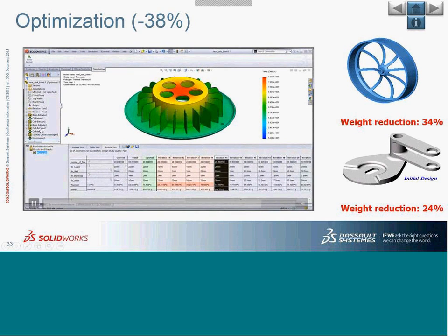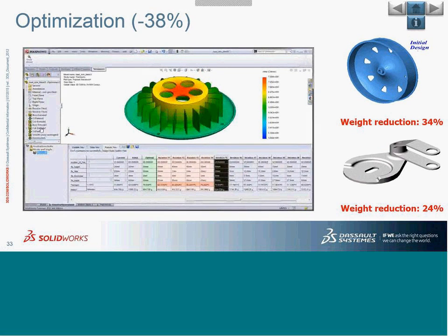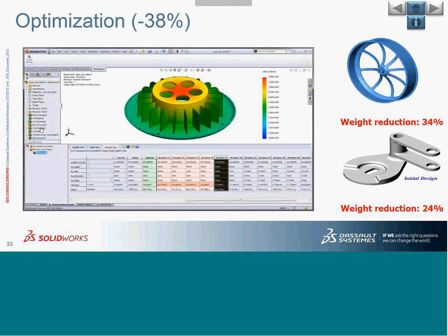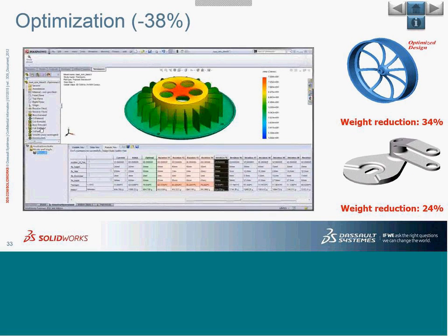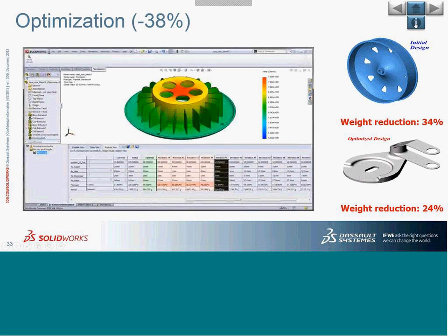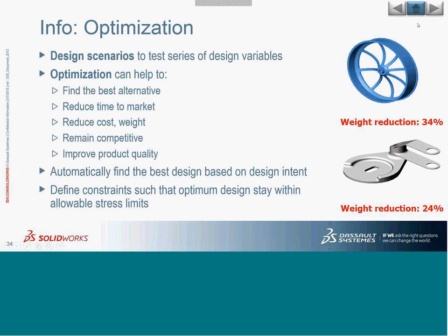Being a parametric model in CAD itself, it can directly talk to SOLIDWORKS and do the appropriate manipulations without loss of geometry. Once it does the optimization, there is a good algorithm which can do the optimization. We get the final geometry which can directly be converted into drawings. You can do any rounding off of the numbers for manufacturability of the components, and you are ready to go. This is how the optimization module works. We'll have a look at this module in the software once more in detail.